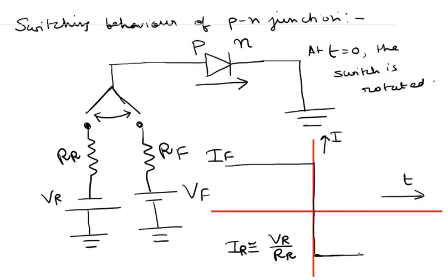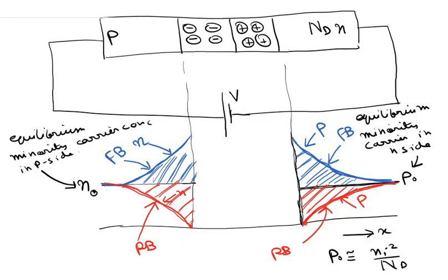Okay, I repeat again that in forward bias state there was accumulation of excess minority carriers just outside the junction. If you don't remember, let me show you the graph. So in the forward bias situation, there was accumulation of excess minority carriers just outside the depletion region, and these minority carriers need to be removed before the diode can actually behave like a reverse bias diode.